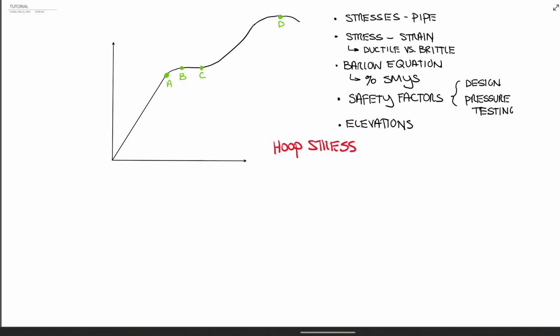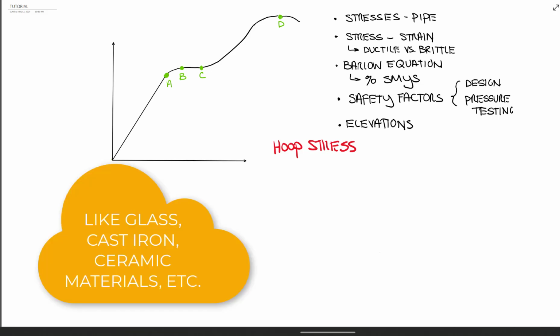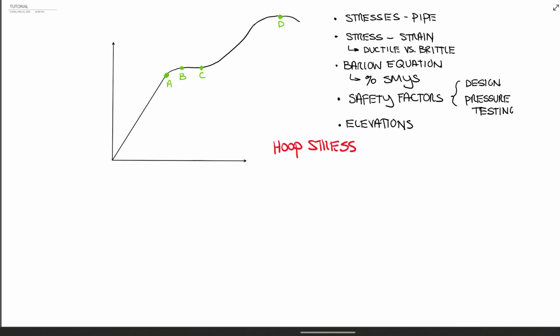Brittle materials are things that are not pliable. In that instance, they just break suddenly, and there's no signs. They just give out. And it's made worse by temperature as well. Materials that are cold become more brittle. And that seems kind of counterintuitive, or intuitive. And then materials that get heated up a little bit become more pliable, and that is intuitive. We would think anything that you heat up would be more malleable. So those are some additional factors.